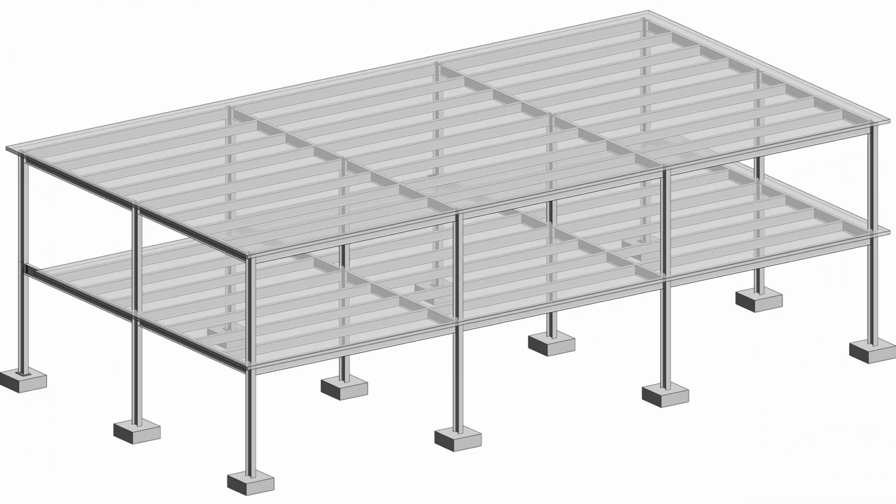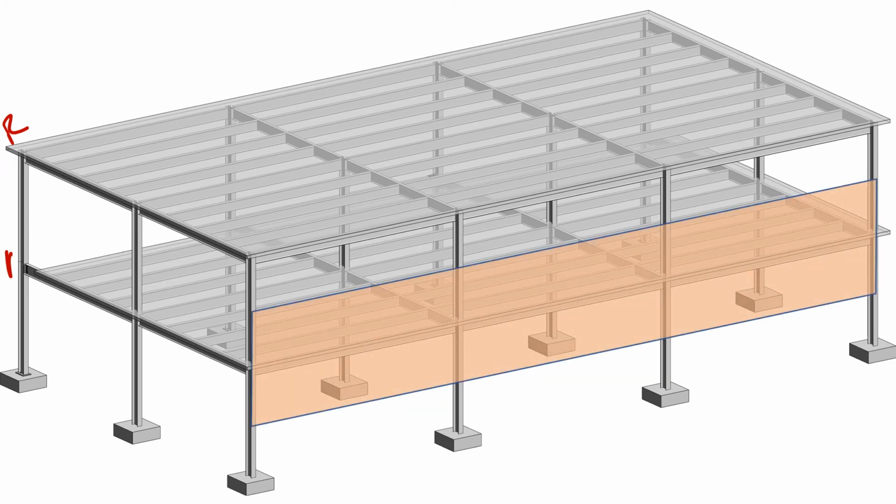So the way that the facade load enters the building depends a lot on how it's attached, but one common way of going about getting these loads into the structure is to define a tributary width. So let's assume that we have a first floor right here and the roof level right there. We might define a tributary width or tributary height for that first floor like this. So that would be the tributary height, call it T sub H.